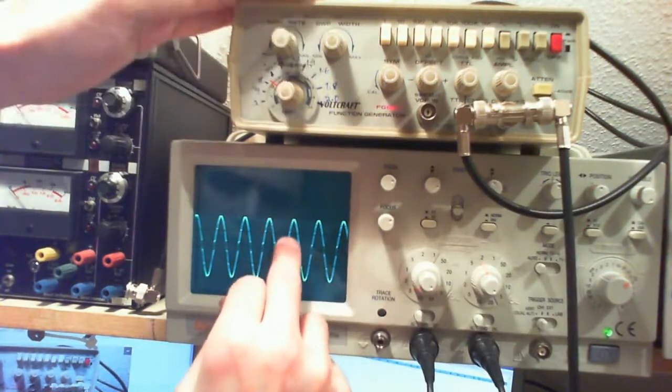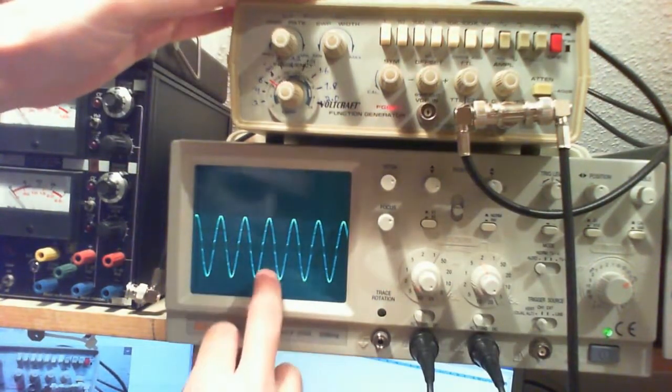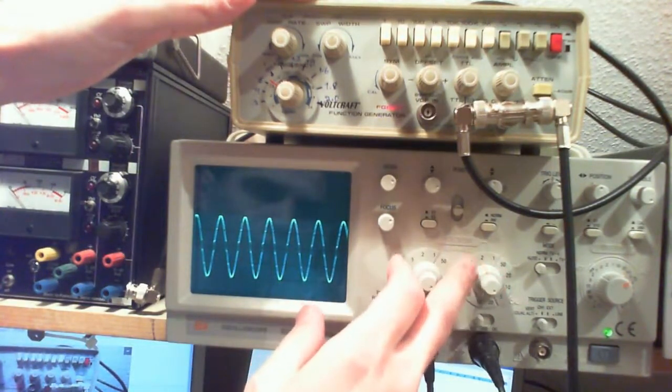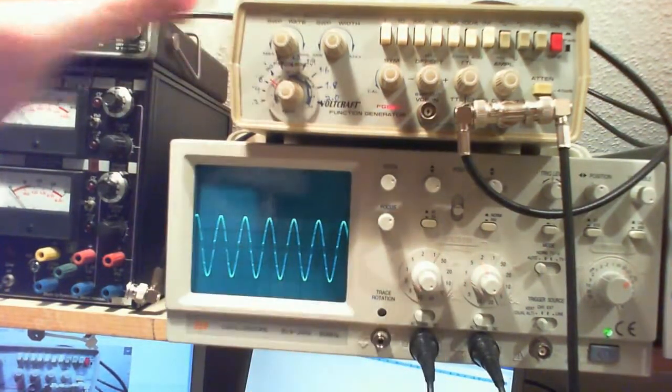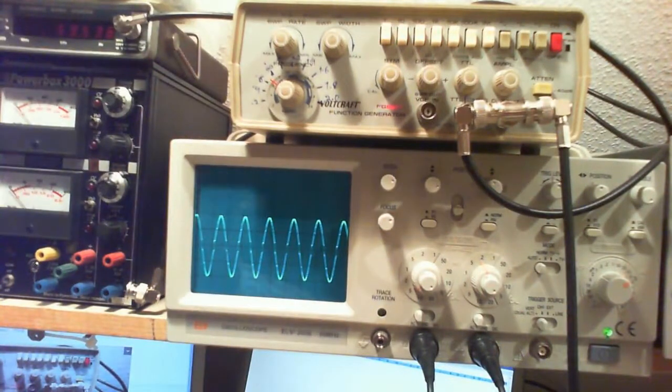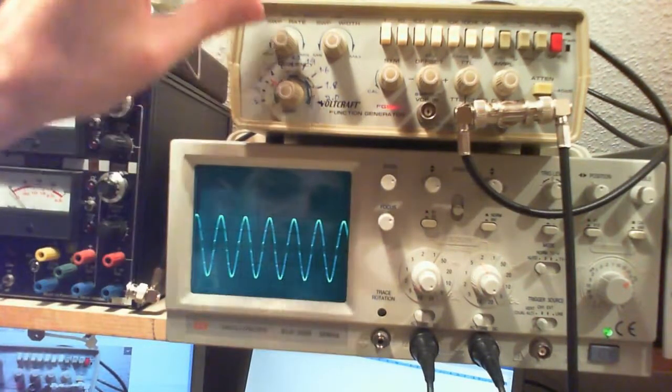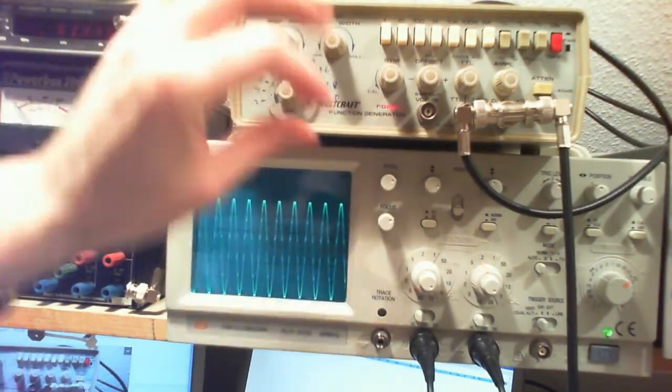And then at 59 kilohertz, your output is at about 1, 2, 3 points. Take it as 4. 4 times 0.2 is equal to 0.8 volts, that's 800 millivolts at 59.5 kilohertz.